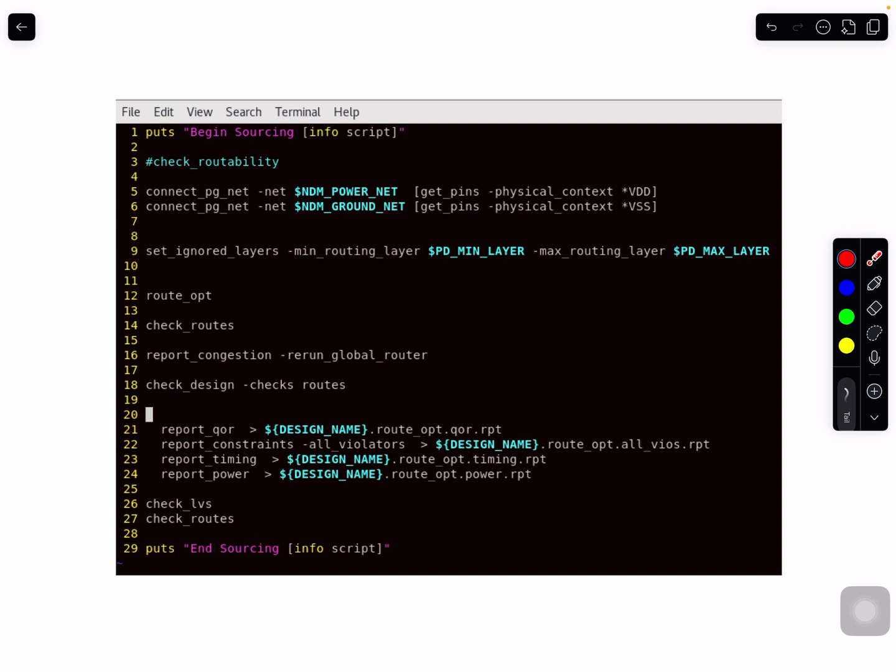Another setting that we need to do is for routing. What metal layers at the SoC level, or in my physical design level on top of standard cells, am I going to use for signal routing? So I had a variable for this one, and I'm just passing it to this command. Later on I will check whether my routing is really using these or not. This is in case you want to limit. You don't want to give the very top 2-3 layers because you have them for something else.